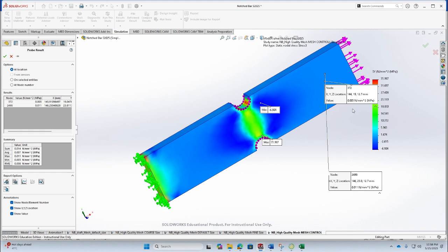But where there is stress concentration, for example along this edge, the stress system is no longer uniform. So you are no longer uniformly pulling it in one direction. Some components will go in other directions as well, and they will be significant, because think about it, 35 megapascal is significant, isn't it, compared to 170, 160, although it's not exactly similar level, but it is still not something that you can simply ignore. You understand? So that's what I want you to plot and reflect.